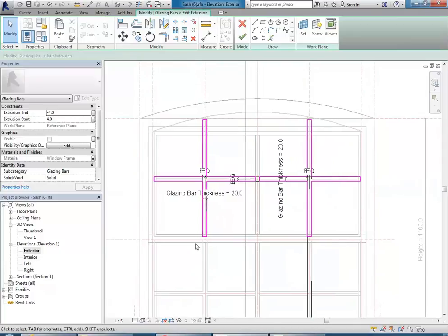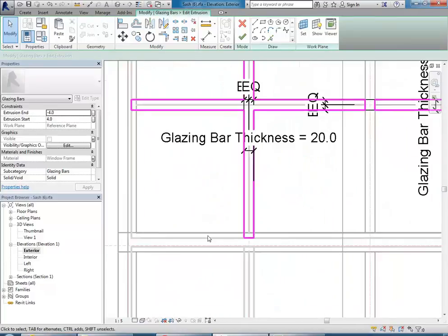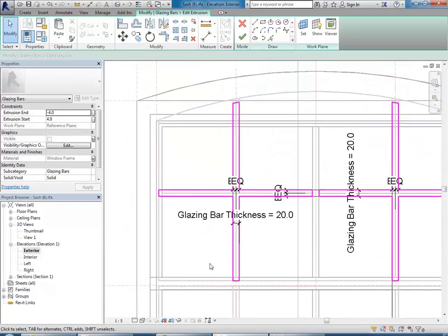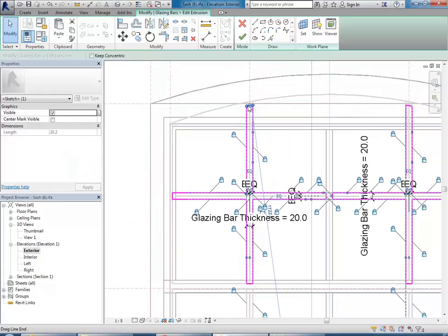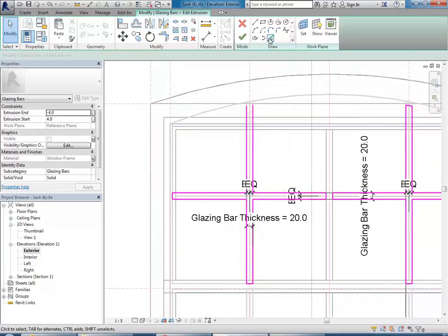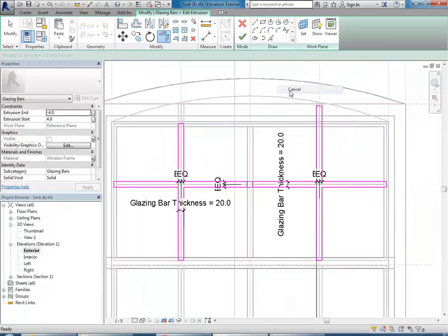And then you can get a better idea how the attaching is set up. And I can again just delete these edges at the top and make a new one with the lock tool turned on, and just make sure I get the right edge. So it's that one there, trim, and then again delete the other one.